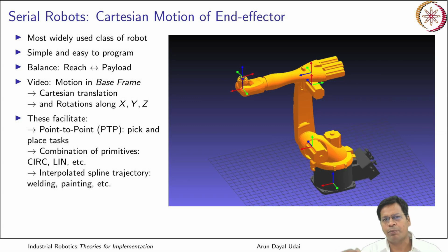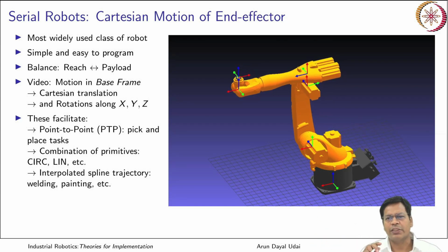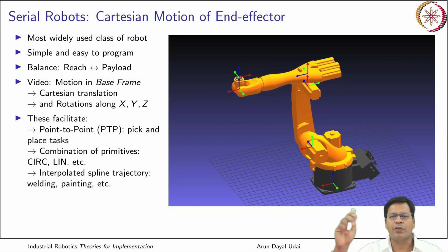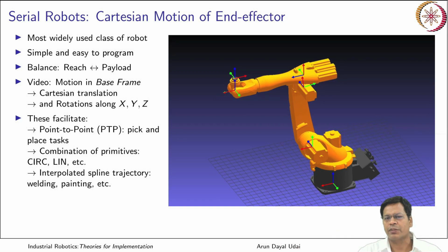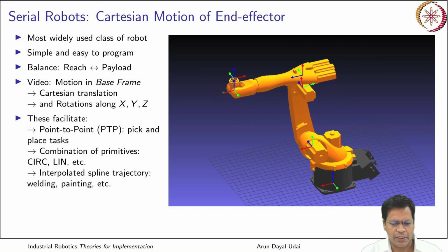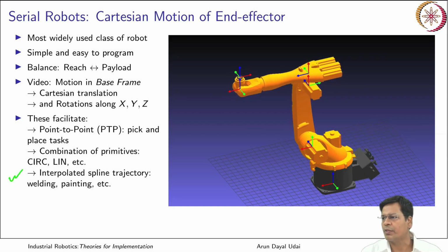Again, when we program, I don't just mean it can go point to point only in position. It will continuously, gradually shift its orientation, which was taught at every location in the workspace. So that is how it can be programmed. This kind of programming is already fitted into this kind of robot's controller.